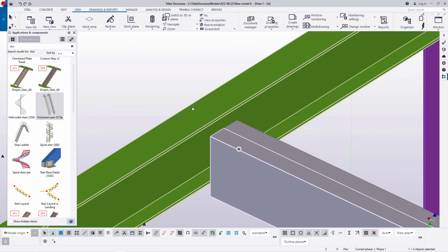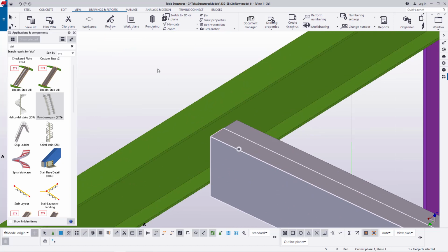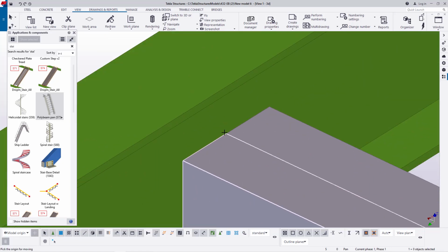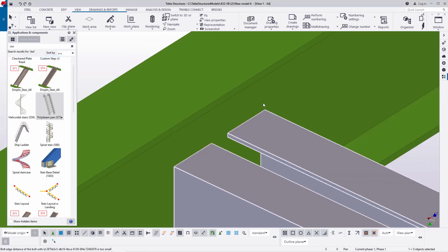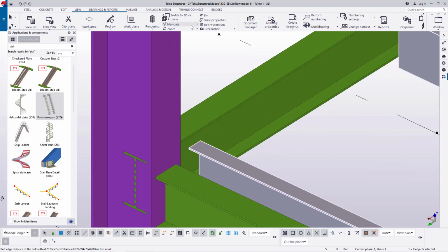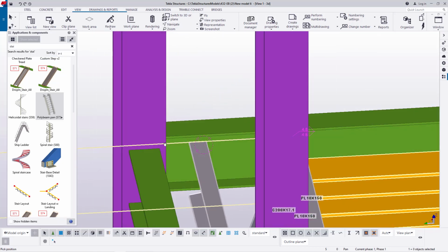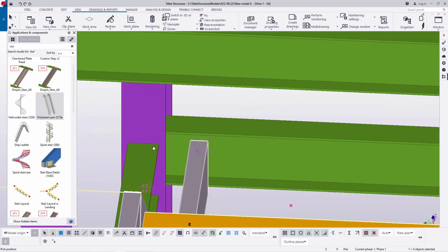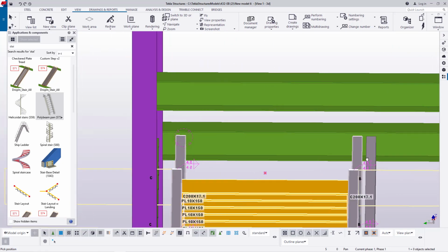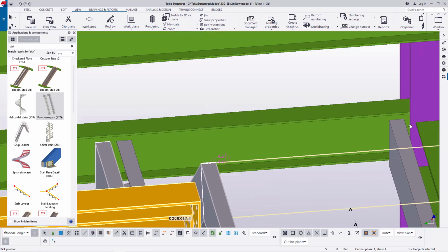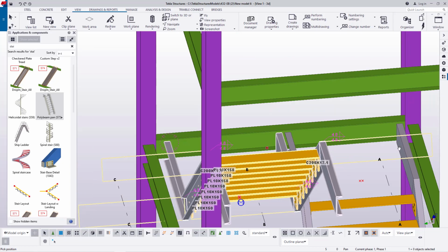Now I'll select on this once again because we need a gap in between the stringer. I'll come to move and pick on that then select on that corner and just place your cursor on that direction and feed in your offset dimensions. And either we can feed 25 as we check on the other end gap remaining. So here we have our staircase in place, and it must be the same. This gap at this far end should be the same with this one.